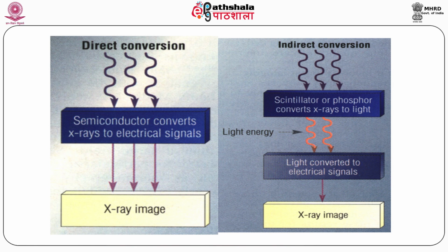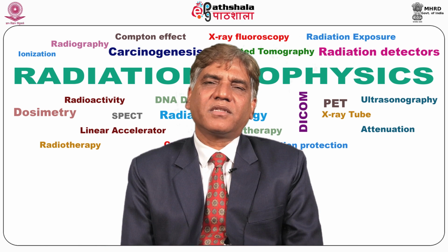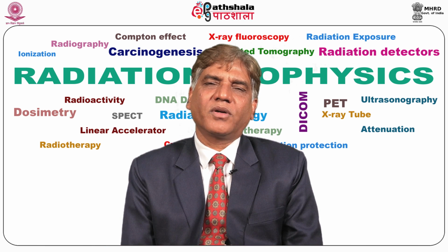An X-ray photoconductor such as an amorphous selenium plate is utilized to directly convert the X-ray photon into electrical charge. Selenium drum based systems are used. Here a rotating selenium drum with a positive electric surface records a charge pattern proportional to the incident X-ray charge during rotation, through an analog to digital converter. And this electrical signal is converted into